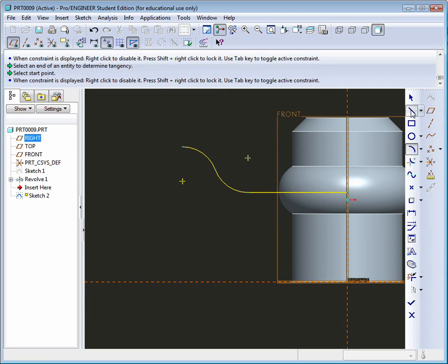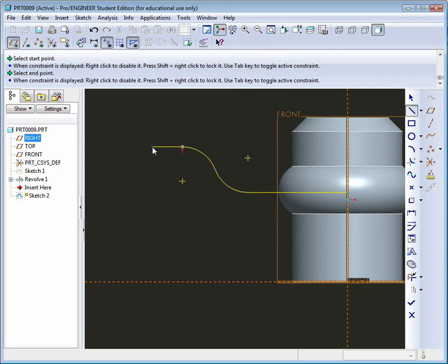And I'll take the line tool and draw a line off of that. And you want it to be horizontal. If we move it down a little bit, you'll see a little T up here. The red T indicates that it's going to apply a tangent relationship. We could do either one. It's not giving us both because it's not perfectly aligned. So we could stick with the tangent relationship, the T there, and then apply a horizontal relationship in just a moment. And then middle click.